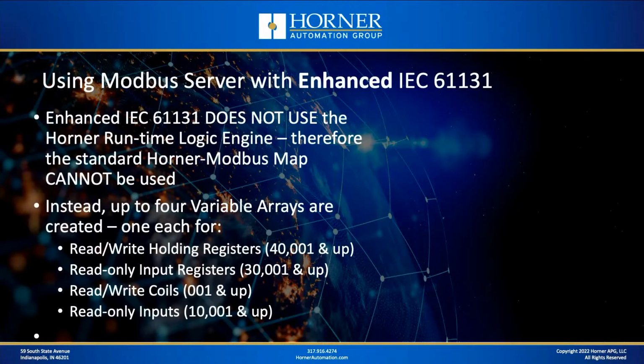Now let's pivot and talk about using Modbus Server with Enhanced IEC, because remember, it uses its own runtime engine, and therefore we cannot use the standard Modbus map with Horner registers, because Horner registers just don't really exist. So instead of that map, we're going to create up to 4 variable arrays in our program, and one each will be used for the holding registers we want to support, the input registers we want to support, any coils we want to support, and any inputs we want to support.